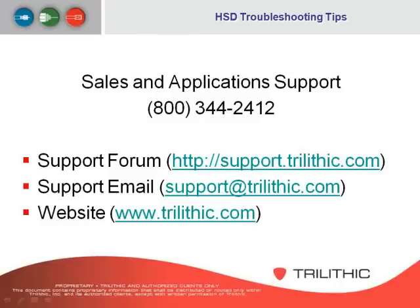I mean, if you have data, it's all the better, because it's looking at exactly what the customer is going to see. But if you're getting a good MER, your BER is probably going to be pretty good, but it's not going to necessarily run one-to-one because it is doing different measurements. The MER is measuring the digital quality itself, similar to a carrier to noise type measurement, whereas the BER is looking for any bits that did not arrive at its destination or that dropped out or whatever the case is. So it's two different measurements, and both are equally important.